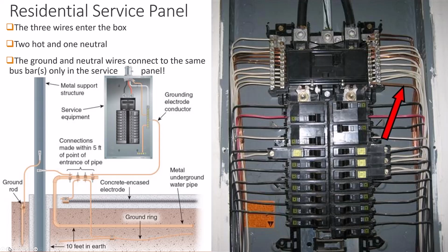In the right-hand picture, in this case, the wires are coming from overhead, like the picture in the previous picture. There's 3 wires that come into your service panel from the meter, and they come from the power pole to the meter and then to this panel. And up at the very top, you see those 3 heavy wires. On each side, the black insulated wires are the hot wires that have 120 or so volts each. And the middle wire is the neutral wire. That's the return path to the power company.